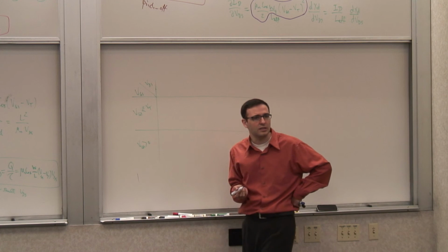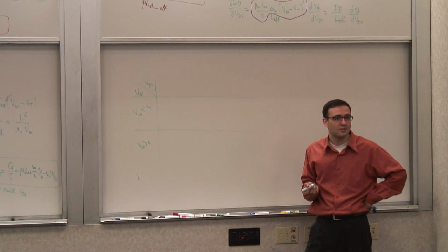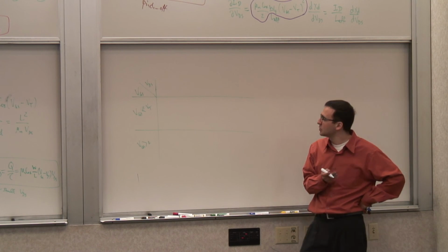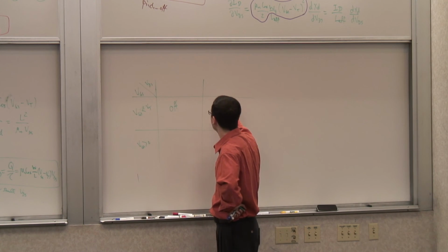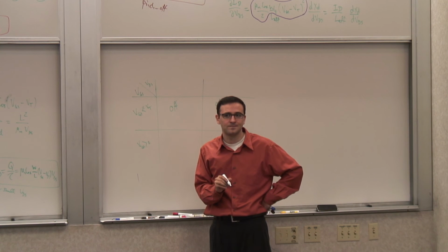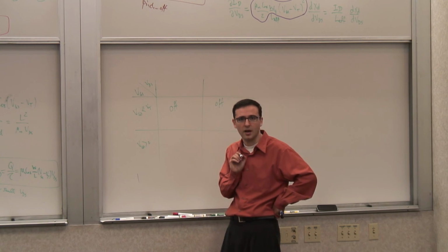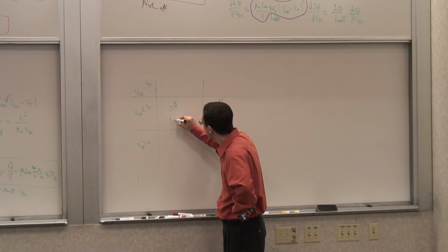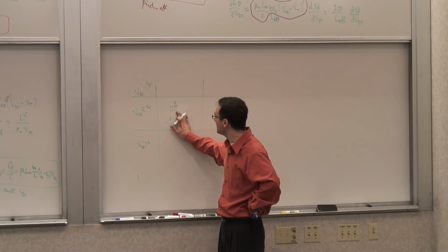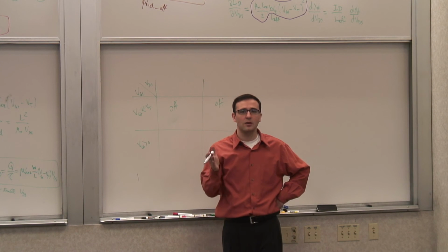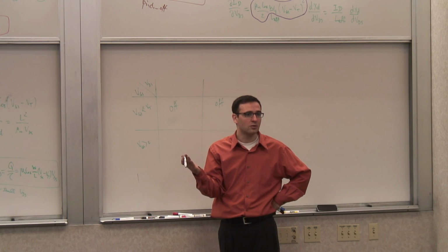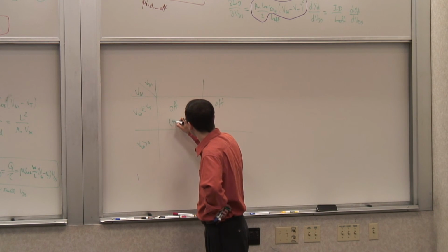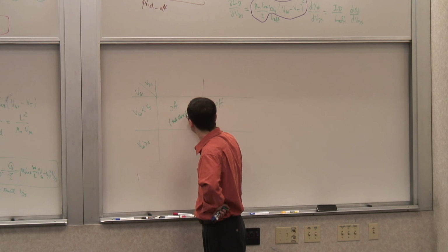If VGS is smaller than VT, what can I say about the transistor? It's off, to first order. For our purposes, we'll say it's off, but what we really know is that it could be in sub-threshold. We'll talk about sub-threshold next time. Off basically means there's no current flow, because based on the simplified model, based on strong inversion, there is no channel charge. But we know there is a little bit of channel charge even before we get to that point, so there could be sub-threshold current.